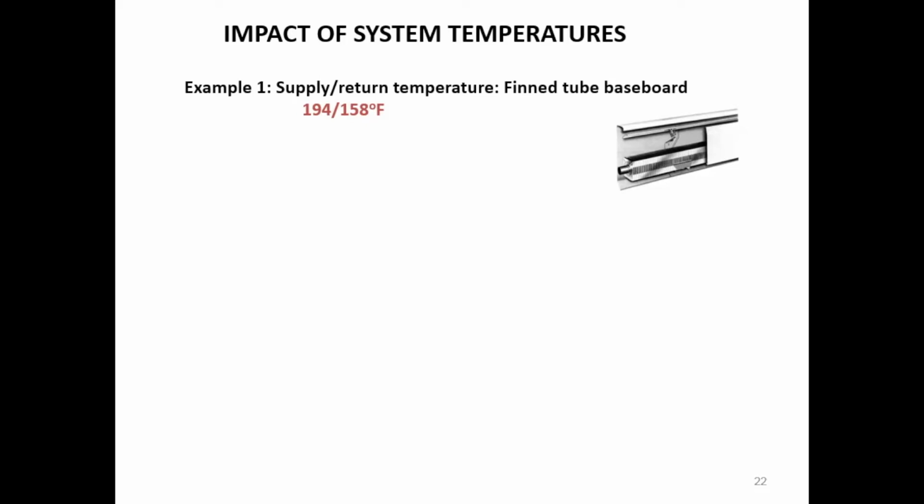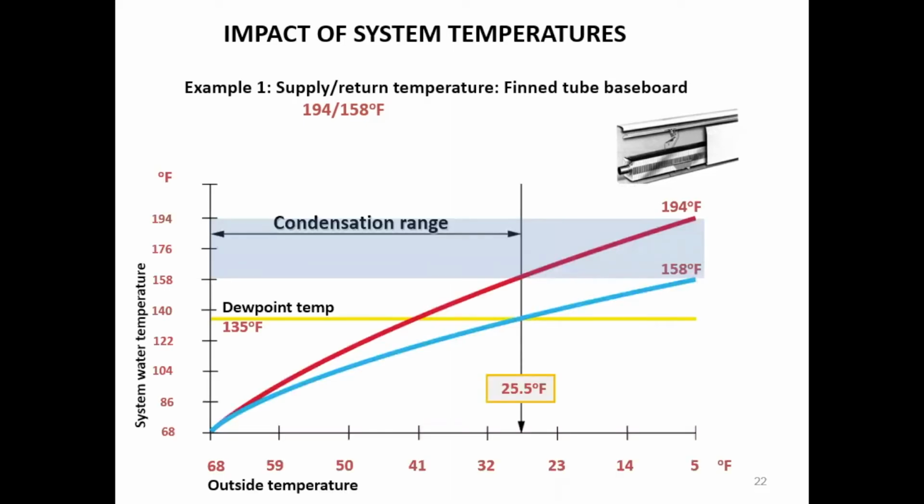So the first thing with water temperature is, now, how do we control? And how we control can cover every single project out there. Then it becomes, what water temperatures can the building live with, or what can we design around? And again, for me, it's all about return water temperature. So we're going to look at a series of slides that look at the impact of return water temperature. And for here, we're looking really at that crossover point from condensing to non-condensing.